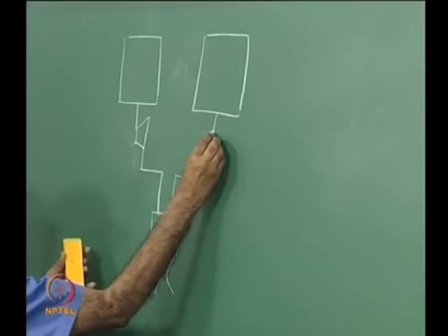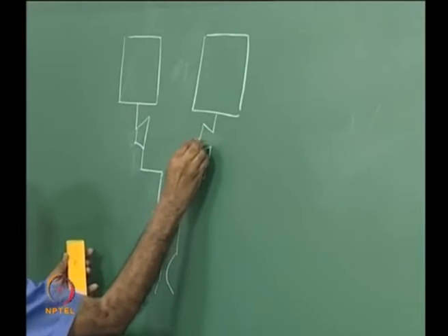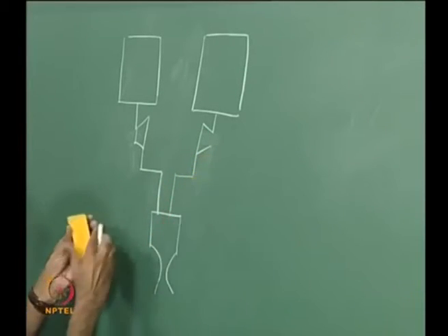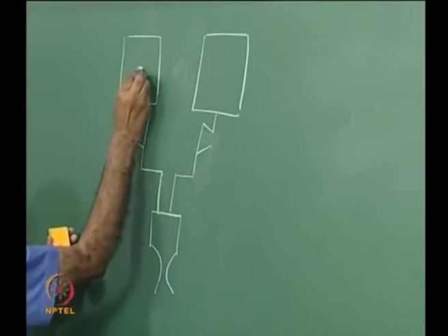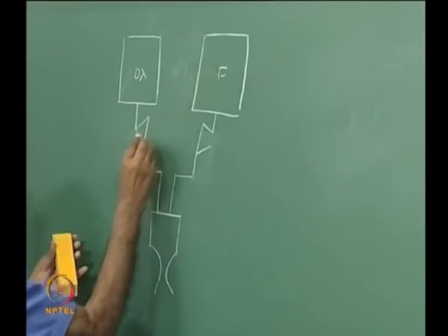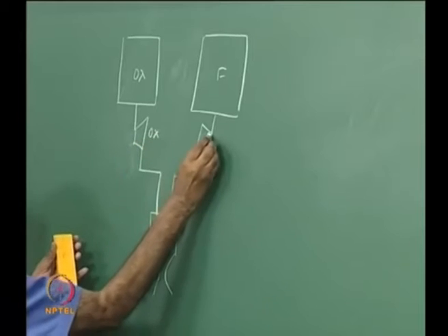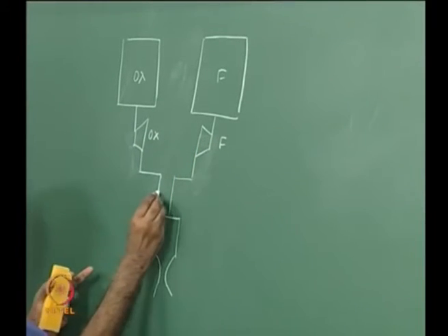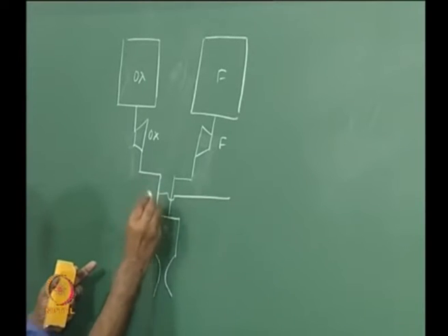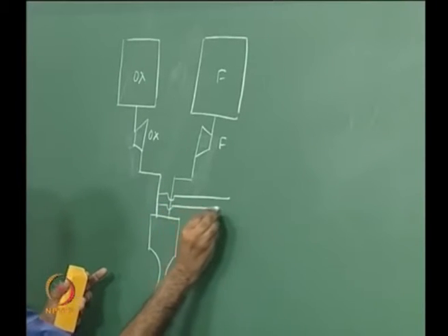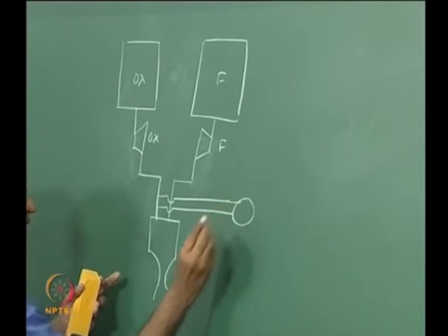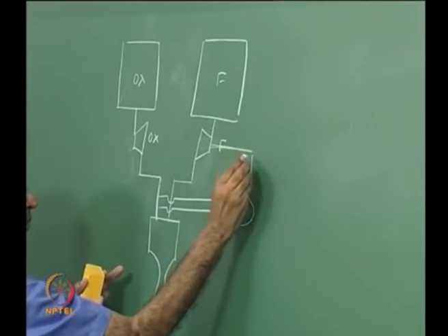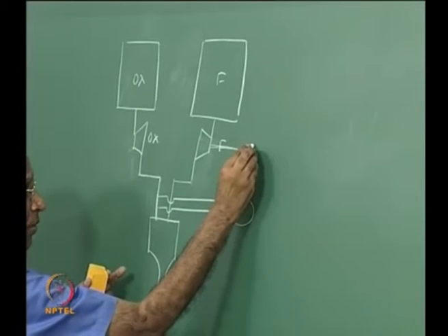Similarly over here, what is it I do? I put a pump over here and then I pump the liquid over here. The second one, maybe this could be oxidizer liquid, this could be fuel liquid; this could be the oxidizer pump, this could be the fuel pump. And then what is it we did? We bled some amount of oxygen or oxidizer, some amount of fuel, burnt it in a gas generator, and then drove the two pumps. That means I put it into a turbine,